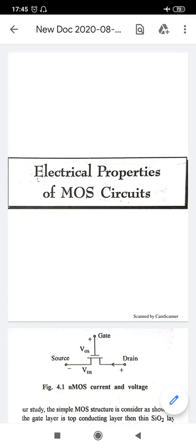quantities. A MOS device conducts electrical current by using an applied voltage to move charge from the source side to the drain side of the device. Since the drain and source are physically separated, the flow of charge underneath the gate can occur only if a conducting path, or channel, has been created between the drain and source. The most important thing I will discuss in this topic is the controlling voltage, because